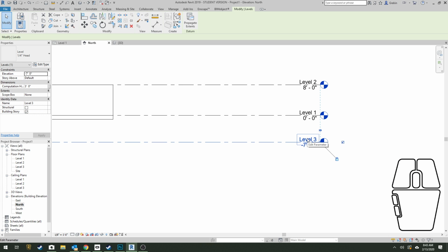So I'm going to add this level here. I'm going to name it. You notice I didn't name my level 1 and level 2. You'll have those named floor and roof. I'm going to name level 3 here. I'm going to call this BO foundation wall, bottom of foundation wall. And I'm going to bring this down to a negative number below my floor level.